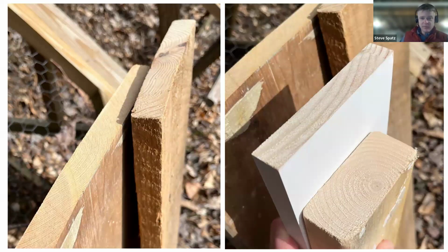But obviously, if you've gone to the lumber yard to try to buy any sort of 2x material, you've probably spent more hours of your life than you'd ever want picking through matchsticks out there in the yard of twisted and cupped and turned lumber. It's what we work with now. It's what we have access to. But you can see, this is an example of the differential in dimensional stability between a tightly grown, slowly grown piece of lumber versus these wide growth rings that have a lot more ability to absorb and transport moisture, which can impact their long-term dimensional stability.